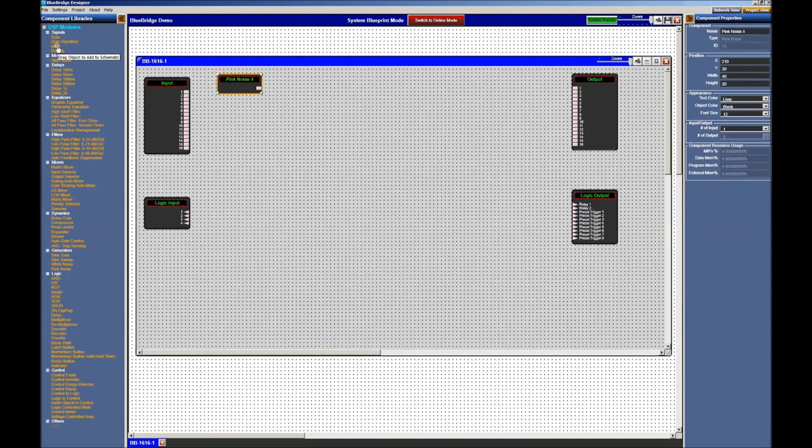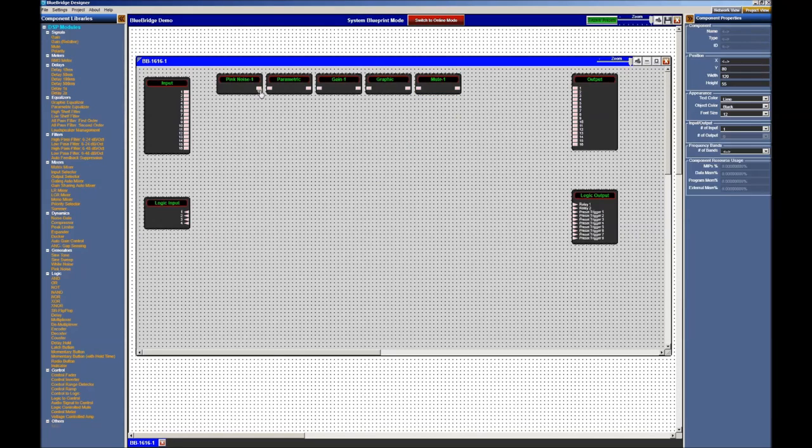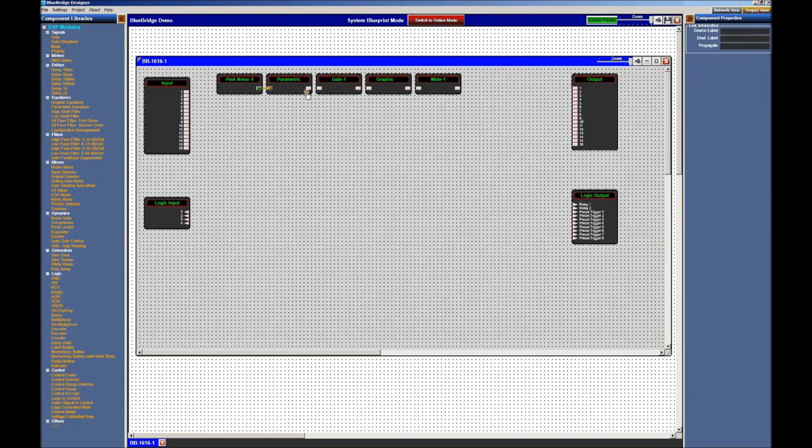We've got a pink noise. The next thing that we had on there was a parametric equalizer, so I'll drag one over, let go of it. Then after that we had a gain, I'll drag one over, let go of it. And then after that we had another equalizer, so we'll put in a graphic EQ just like in the original. And then finally we had a mute before passing this off to the output. So that's one set.